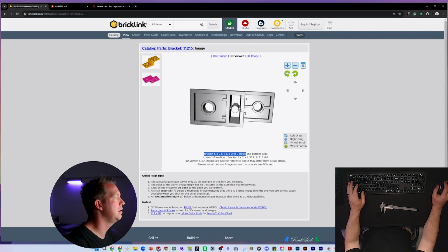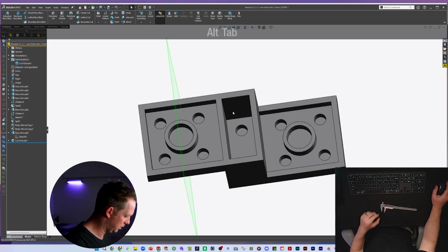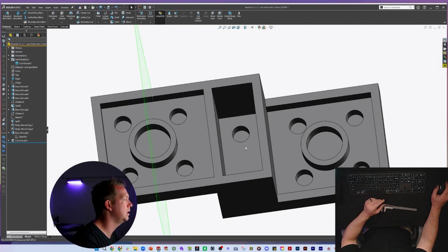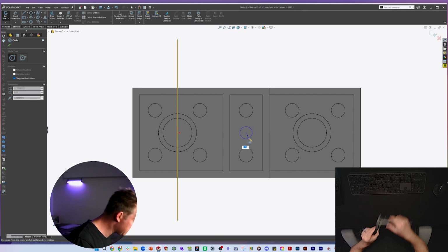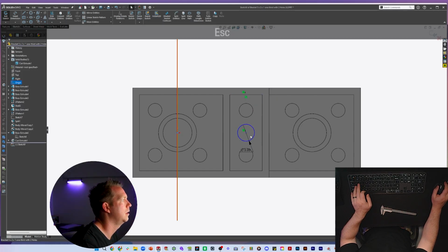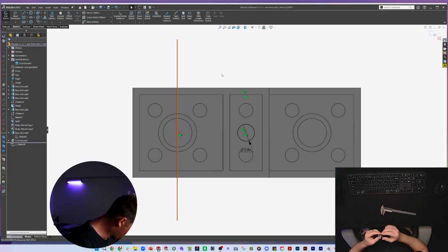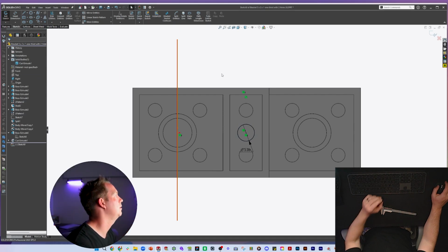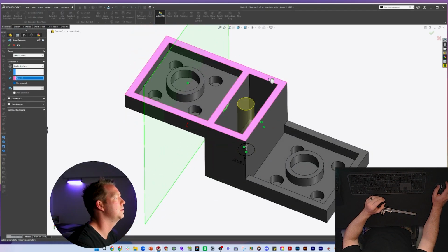Here, it's got a pin with a thin rib. So let's put that little pin and rib detail in. A circle with about 3 millimeters, and it is in the middle of this part and in line with the origin. Now the ribs don't go all the way to the top, so we'll do them separately. This one will be an extrude, come up to this surface.